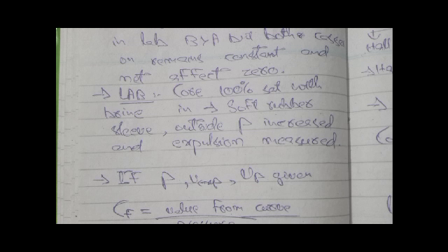And in the second phase of the experiment, we move the water now by oil. We pour the water saturated rock into the oil chamber, the container full of oil, and then we do spontaneous imbibition, in which the water inside the rock moves out and oil moves in. Then we remove the remaining water, which would be residual water, and we measure the amount that came out and the time that it took.